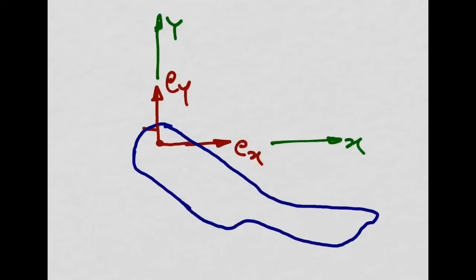Don't forget, these Cx and Cy in red are the reactions on the part that we isolated that was in red color, right? But now we also have the same point C for this part in blue. So basically this Cx and Cy in red was the action of this part in blue into the part in red.